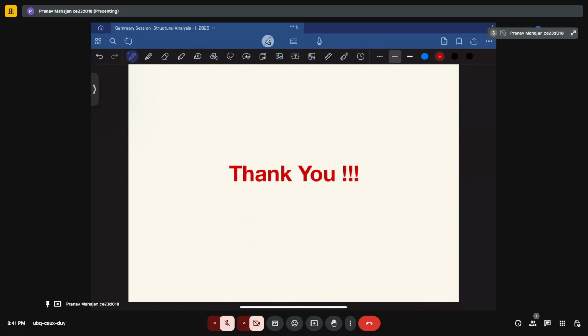The moment distribution method is based upon the distribution factor. So how will you calculate the distribution factor? First, we calculate all the stiffnesses at that particular joint using the far end conditions. Based upon the far end condition, you calculate the stiffness at that joint, and then you distribute based upon their values, divided by the sum of the total stiffness coming over the section. After doing that, you will use the moment distribution method.